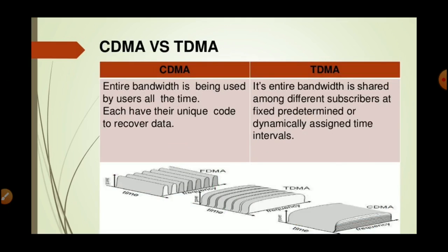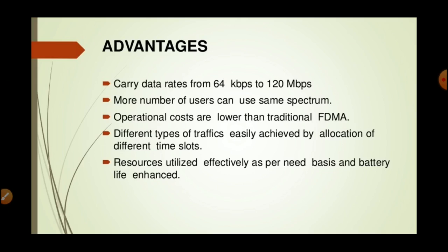CDMA versus TDMA. In CDMA, the entire bandwidth is being used by users all the time, each having their unique code to recover data. In TDMA, the entire bandwidth is shared among different subscribers at fixed, predetermined, or dynamically assigned time intervals.